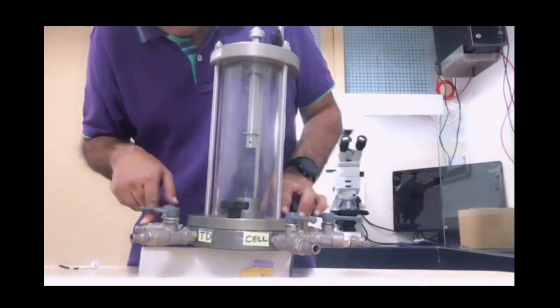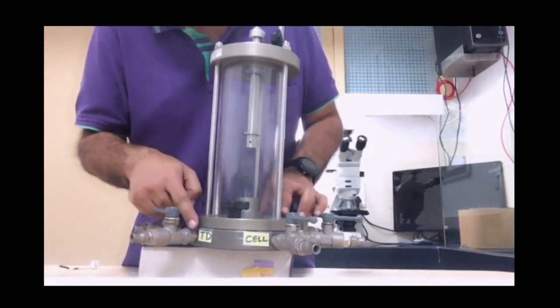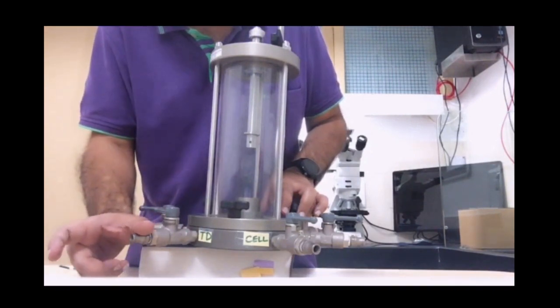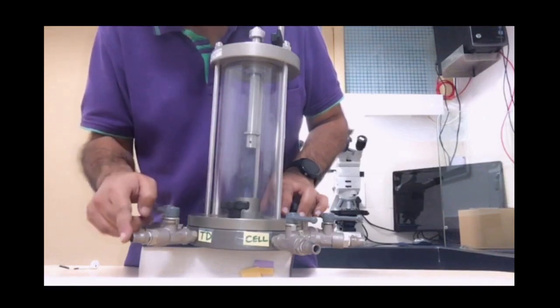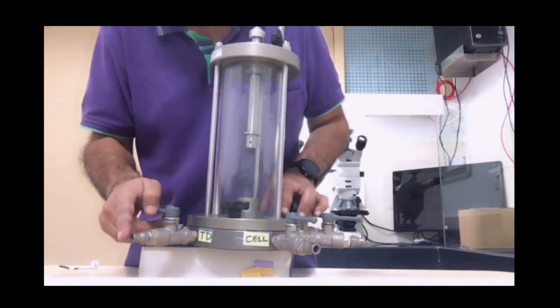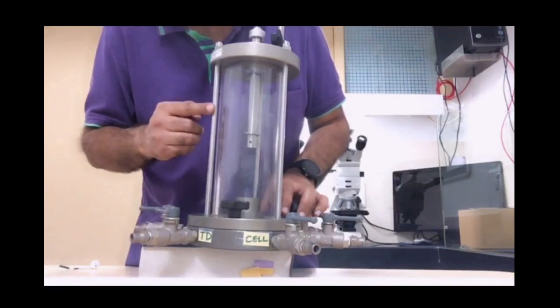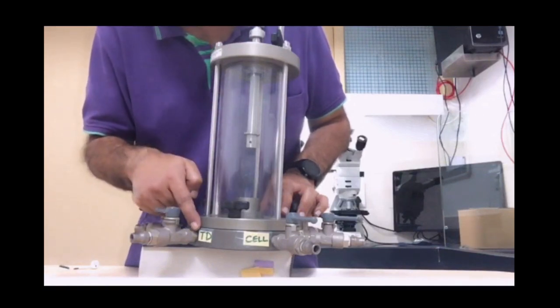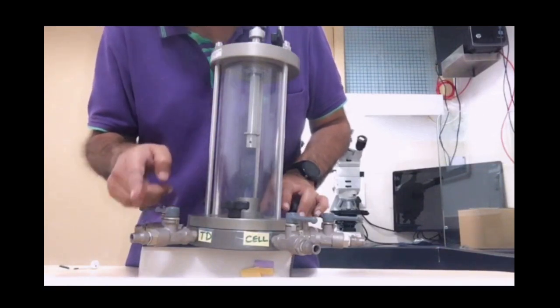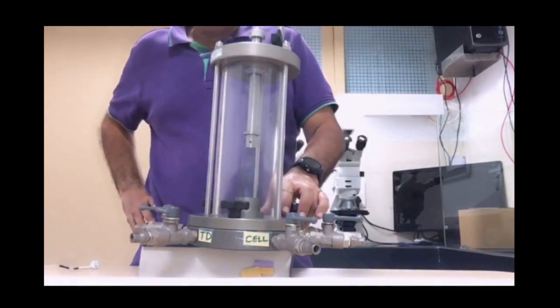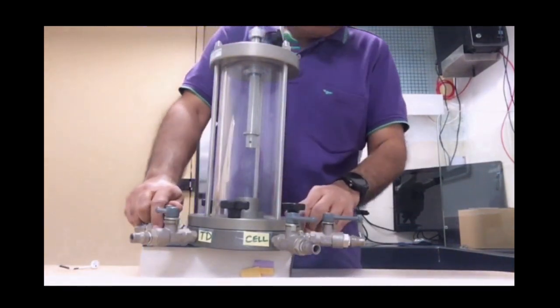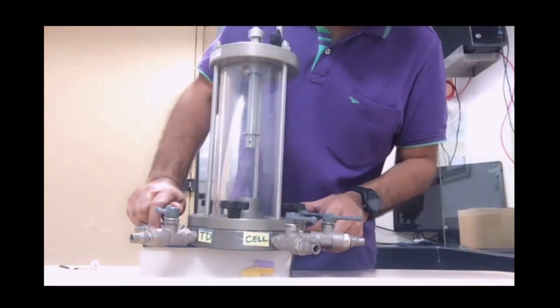You may have a situation where instead of this top drainage, I can connect a gauge over here. So the gauge is now connected to the top of the sample. I can then read out what my pore pressure reading is at the top of the sample. Remember, I'm just using this for dual purpose. Instead of top drainage, I use it for pore pressure reading. I connect a PPT to it.